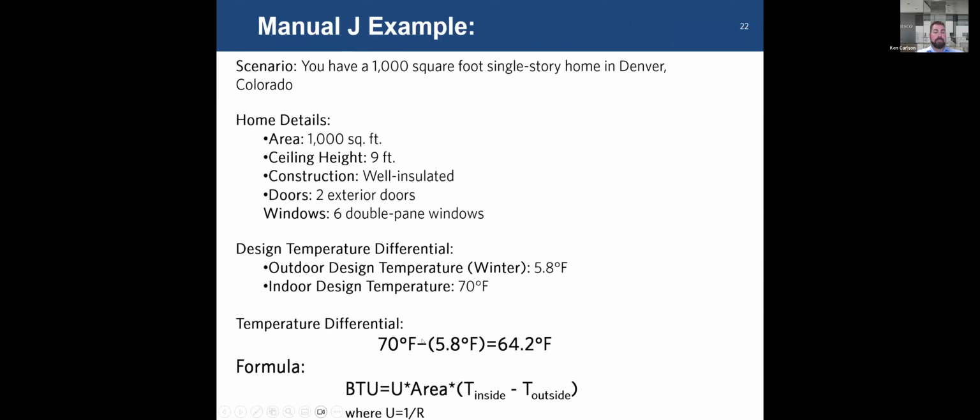So first and foremost, heat loss, right? Heat loss is calculated with this formula down at the bottom. BTUs equals the U value, which is the coefficient of thermal transmittance. It is the opposite of an R value, which is the coefficient of thermal resistance. Everybody's probably seen insulation has an R value, R10, 20, 30, right? 1 over R is your U value. So the higher the R value, the less transmittant, the less that material transfers energy, because of this inverse relationship.